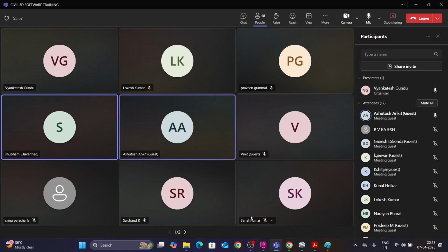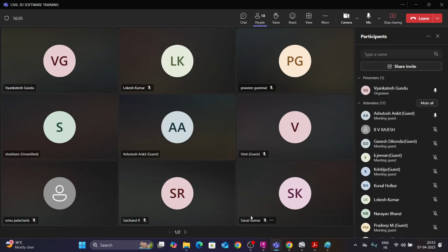I was asking, that gradient should be limiting gradient, decided on the basis of the terrain. In the IRC code, you can go through the IRC 2-lane code. They have given values for the plain terrain, hilly terrain, and more. There is ruling gradient, limiting gradient, exceptional gradient. There are three types of gradient. I am telling, 7% is the maximum gradient that we can provide, and minimum is 0.33. For the drainage purpose, minimum gradient should be 0.33.